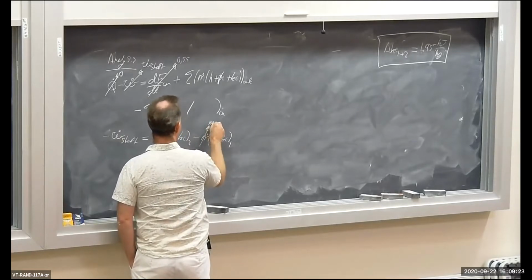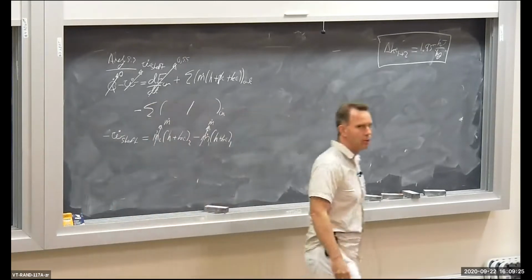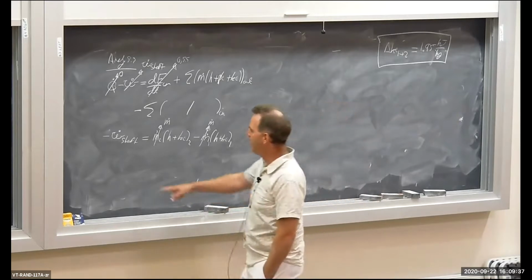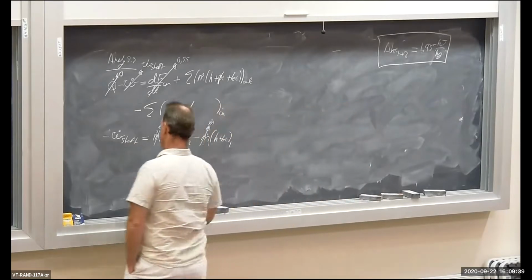If you want to prove that, you can go through the mass balance. You're going to see that M dot 1 is equal to M dot 2, and I'm just going to call them M dot. Okay, let me group together the enthalpy term and the change in kinetic energy term, and I'll have my final version. And I'll also distribute the negative sign.